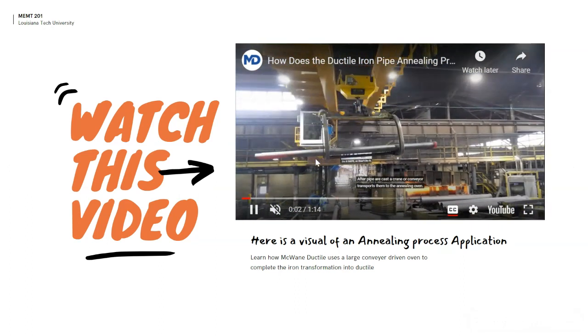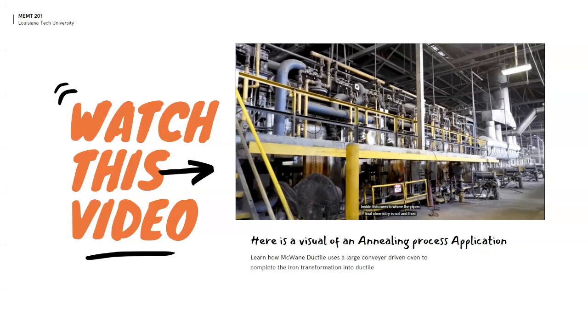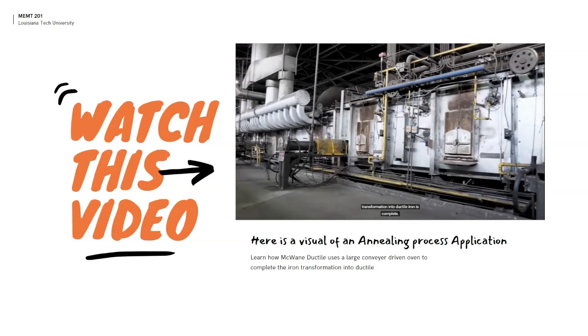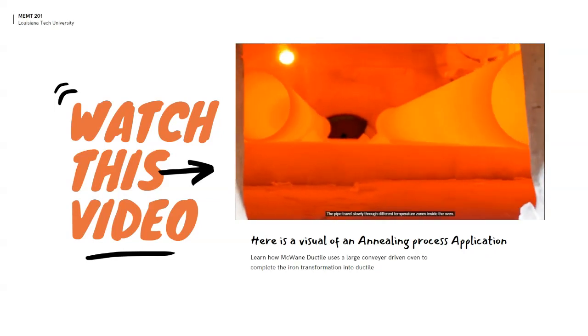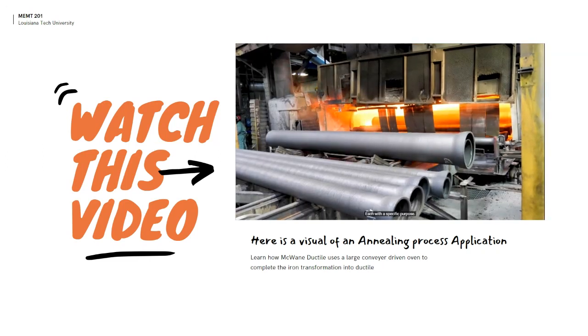After pipe are cast, a crane or conveyor transports them to the annealing oven. Inside this oven is where the pipe's final chemistry is set, and their transformation into ductile iron is complete. The pipe travels slowly through different temperature zones inside the oven, each with a specific purpose.